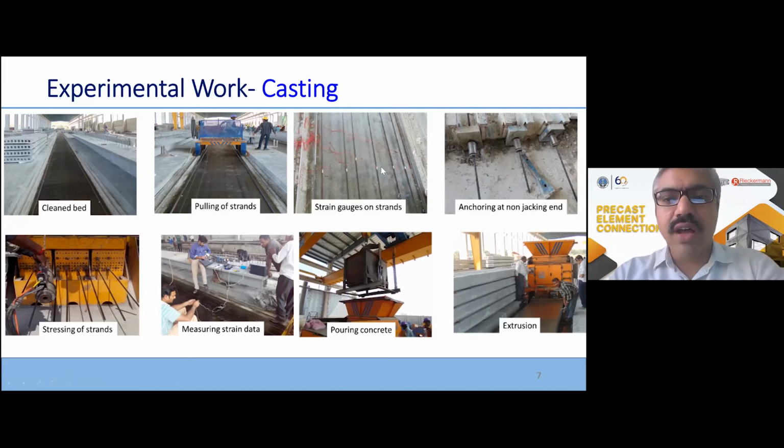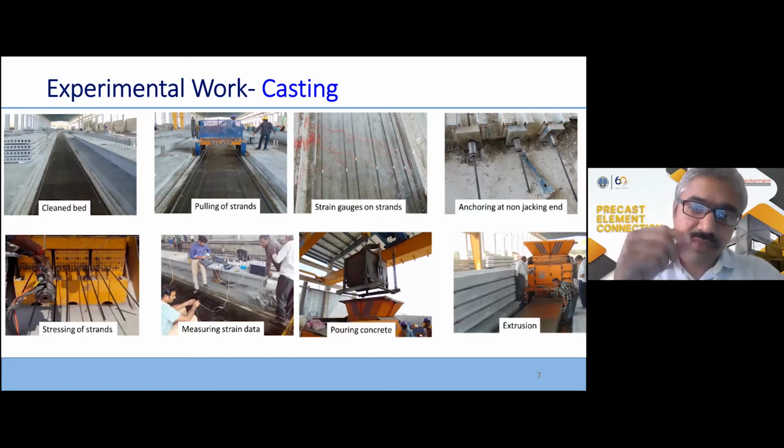And for our experimental work, we had placed several strain gauges on the strands to measure the pre-stressing force, the stress in the strands, as well as the losses which occur, so that we get the exact amount of pre-stressing force left in the strands. And you can see the anchorage at the non-jacking end, and after that the strands are stressed, and we were measuring the strain data in the strands while the pre-stressing is going on.